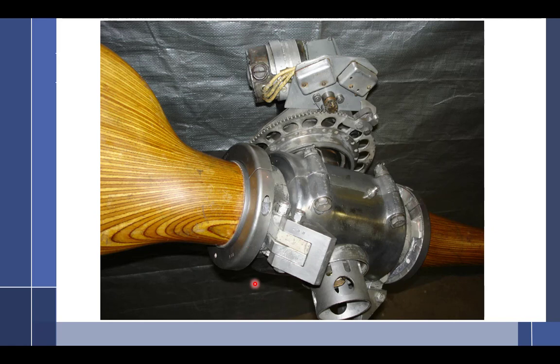This particular one was electric and had a little switch. So you can put a little more pitch and a little less pitch, a little more pitch, a little less pitch. And this electric motor would move the little pinion, which moved the gear, and it would move the blades. So the governor was manual? Yep, manual governor. So you would just dial in whatever pitch you want. A little more pitch, a little less pitch.